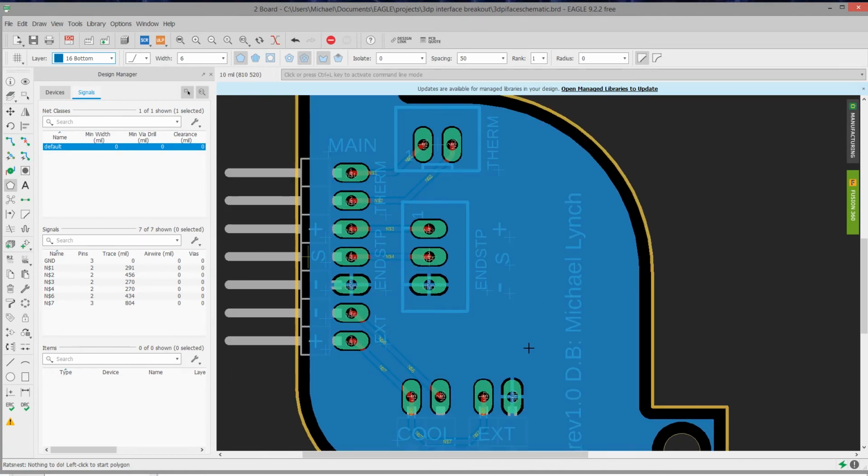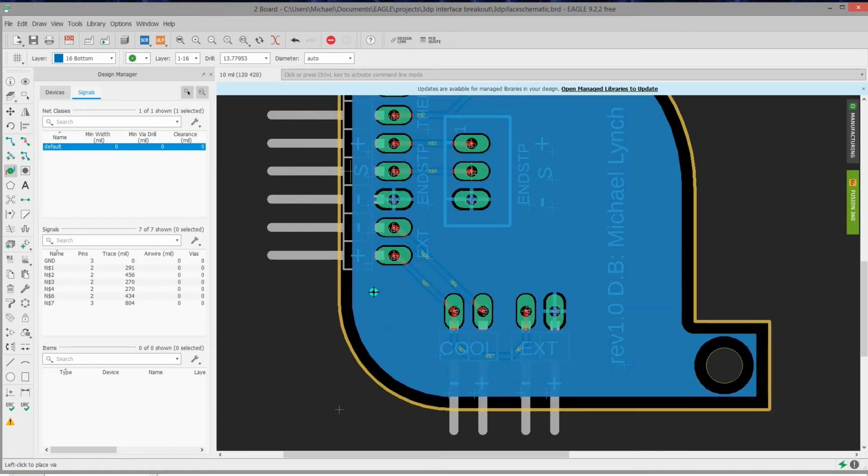Another good practice for these is to make some vias. These are basically contacts that go between both sides of the board. You can use them to connect contacts that may be in a dead end area on one side but may be freed up on the other. For instance, if you have a big integrated circuit, like an Arduino or an Atmel style chip with contacts on all four sides, you might have to go in the middle of the chip just to where the contacts are, just to make some things connect to each other. So I want to go ahead and litter these all over the place.